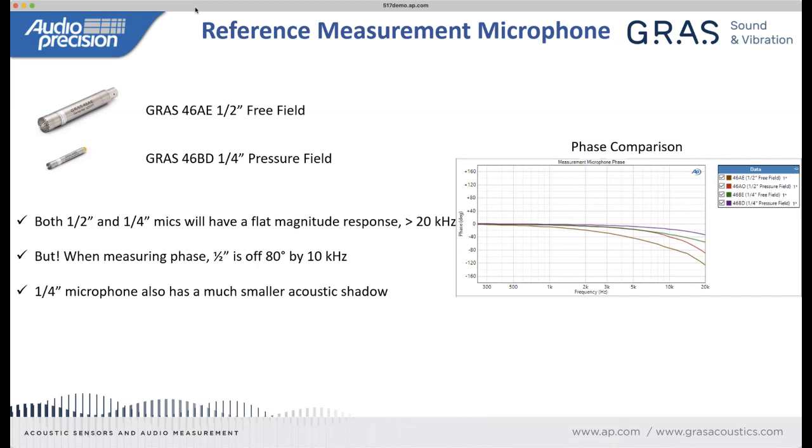But particularly if we're looking at phase response, and that's often a key question when we're measuring microphone arrays, MEMS microphone arrays for, say, smart speaker applications, we're really very interested in the phase response of our individual microphones under test. Then there's a pretty big difference. For a standard half-inch microphone, the phase response is only flat up to about 1 kilohertz, and then it starts rolling off.